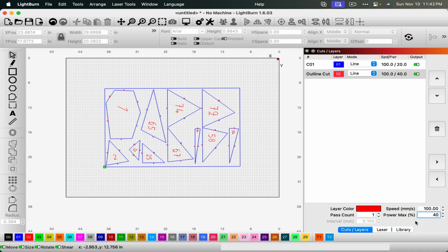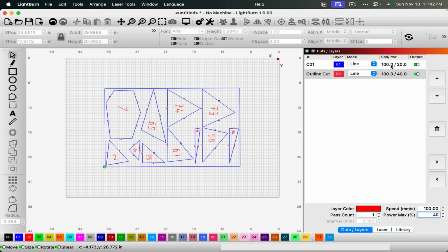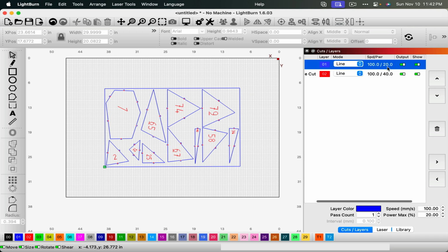There is a little cardboard template in the laser cutter room that gives you an idea, because you just want these numbers to be etched in. Now we can click on this, and we want to go down in speed, down to, let's do like 40, and then power 70. And that should give plenty to cut. It's always good to try this stuff.